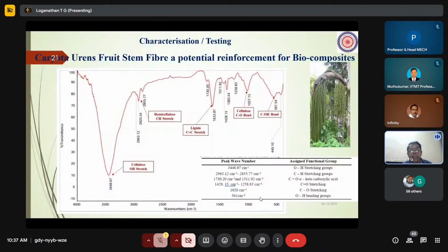As we understood this, we then identified silane. Silane is one of the sizing agents, so it is going to be used as a fiber sizing agent, and we have treated the fiber and studied the mechanical properties as well. These types of tests enable us to identify which sizing agent is suitable for the fiber. As the hydroxyl group has a high intensity, we went for this silane.